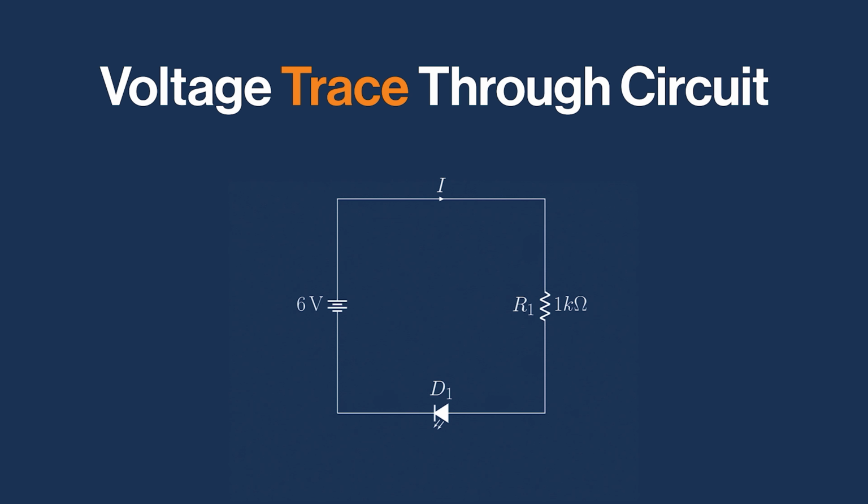Cool. Now that we have done the polarity, let's trace the voltage in our circuit. Let's walk through it and see how the voltage behaves or changes in the circuit you just built. Step 1. Current starts at the battery's positive terminal at 6 volts. Then it travels through the wire, still at 6 volts. It then passes through the resistor.